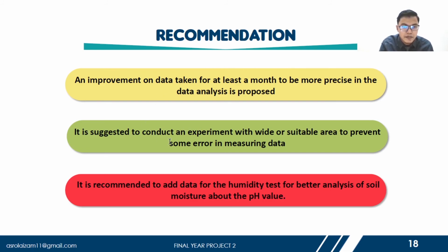I also suggest conducting the experiment in a wide and suitable area with no limitation when scaling the distance between the roads, so we can prevent some errors in measuring data. And the last recommendation is to add a humidity test, so we can have better analysis of the soil moisture and the pH value.